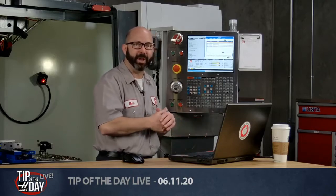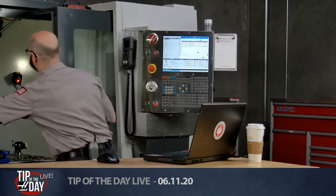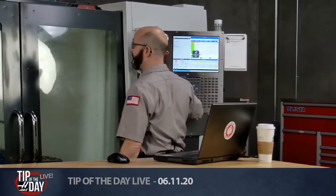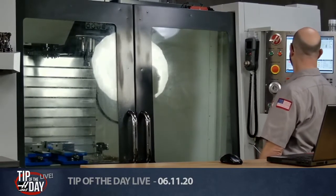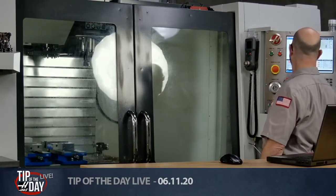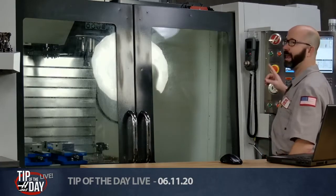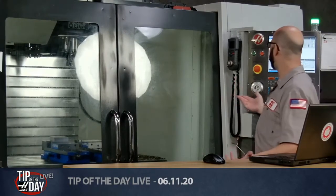That's setting 21. But we also have a new feature if you've got an NGC mill or lathe, which is tied to our G0 rapid command. So if I wanted to rapid across this part, which I will do, I'm going to type G0, G91, X minus 15. That's a rapid move. That should rapid from one side of the table to the other. Right there, 15 inches, that's fairly fast.